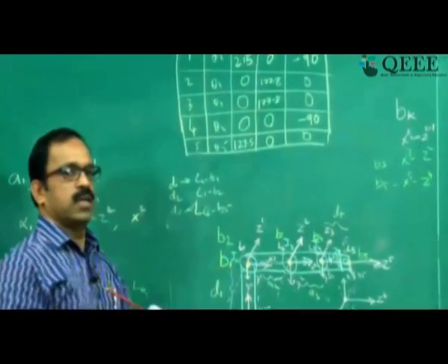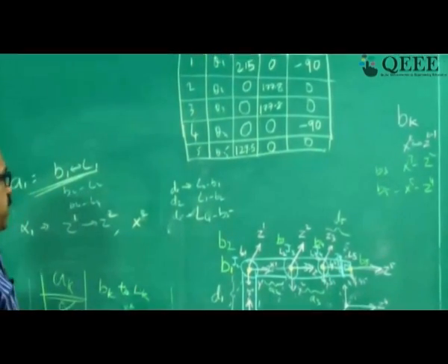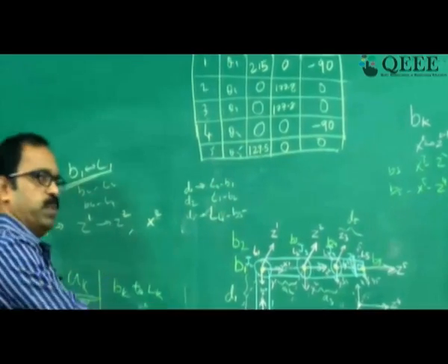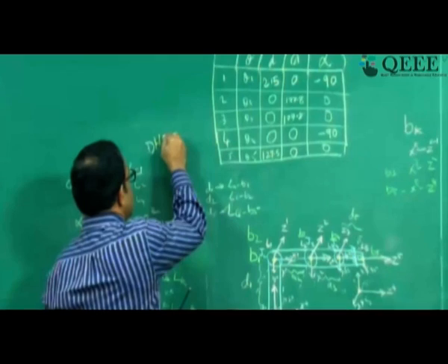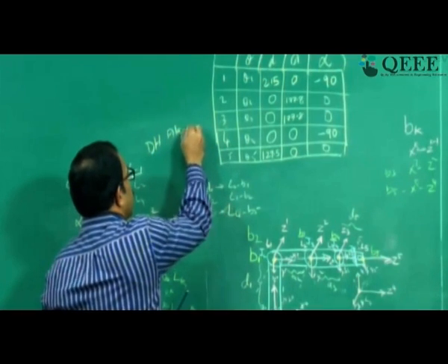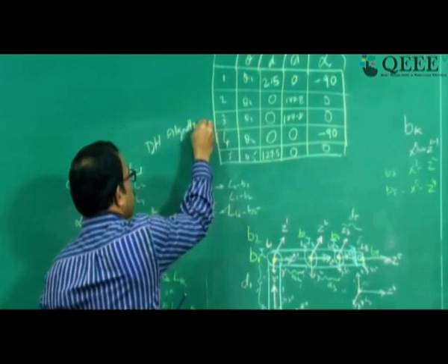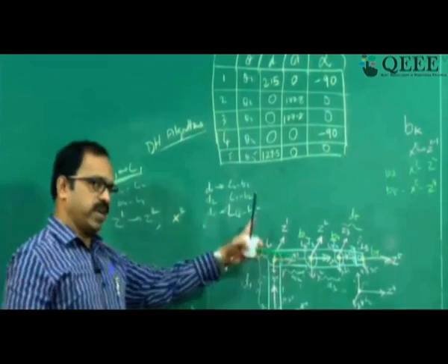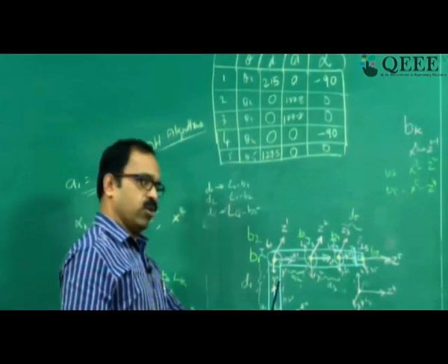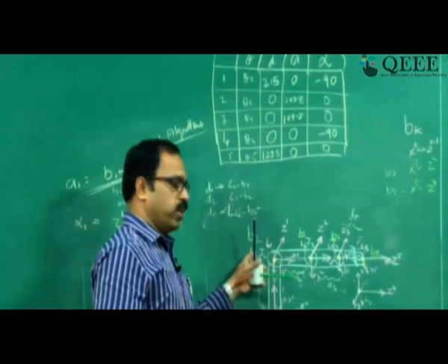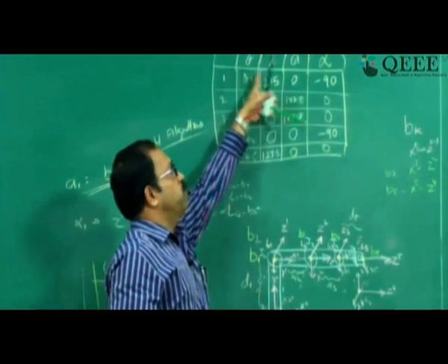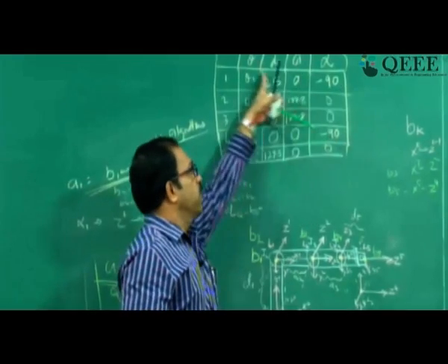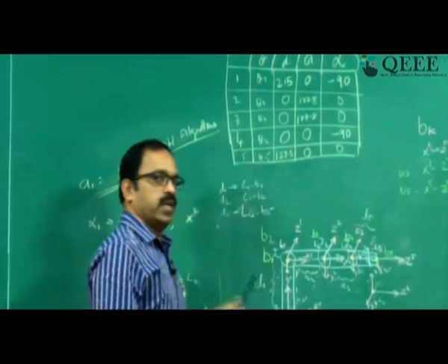So by assigning coordinate frames and then looking at the B's and L's, we are able to identify all the kinematic parameters, or the DH parameters, of the manipulator. That is the DH algorithm. The DH algorithm gives you a systematic approach to assign coordinate frames, assign the origins, get the points BK, and then get all the DH joint parameters and link parameters from the manipulator configuration.